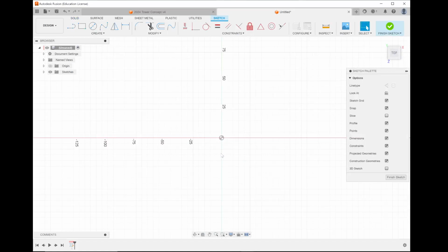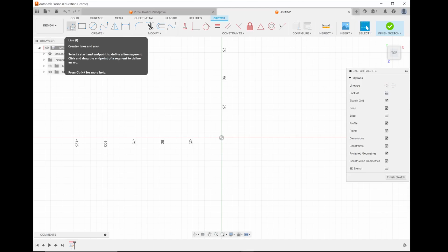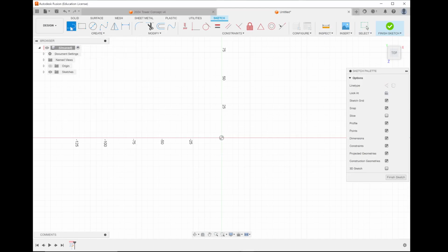Now notice how it went from 3D to 2D. I'm going to draw my 2D shape now. I want to draw the box, so I am going to press this line tool over here. I am going to press it in the center, and now as I go, see how I'm dragging out this line. I can make this 2D line. We're just going to make a box, which is a very simple shape. If I hold my arrow going up, we see how it says 90 degrees. And see how this box on the left has 41.724. I can type numbers in there, and Fusion 360 will work with that.